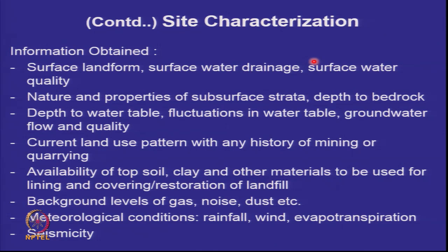And it's not simple. You have to have the following information: surface landform topography, drainage and surface water quality, subsoil properties, depth to bedrock, depth to water table, fluctuations in water table, what is the direction of groundwater flow and what is the quality, current land use pattern with any history of mining or quarrying, are there any underground openings, availability of topsoil, clay and other materials to be used for the landfill, what are the background levels of gas, noise, dust, etc., which you are going to later monitor, and the meteorological conditions, rainfall, wind, evapotranspiration and seismicity.